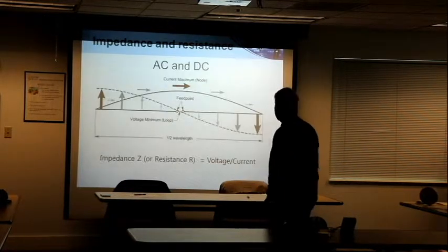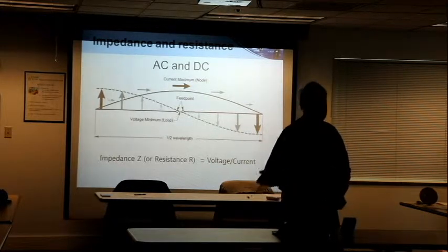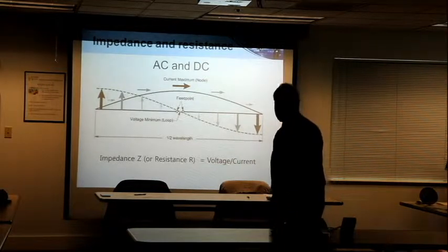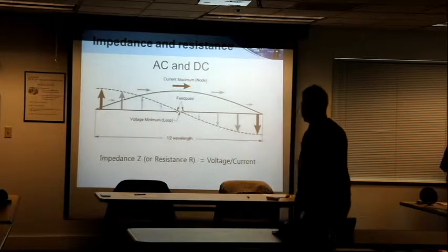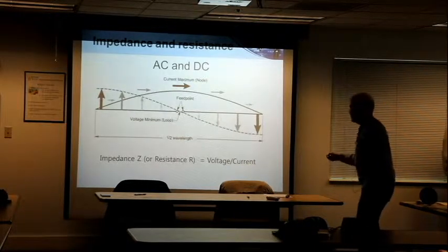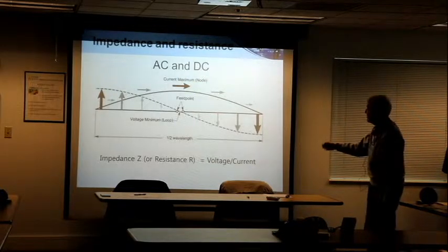Slide, please. Thank you. Okay, remember when we had the first session a couple of months ago, we showed a half-wave antenna? This is just reminding you of that. Notice that the solid curve at the top here, which represents the current flowing in this half-wave antenna, has a maximum at the feed point or the center and a minimum at the other end.